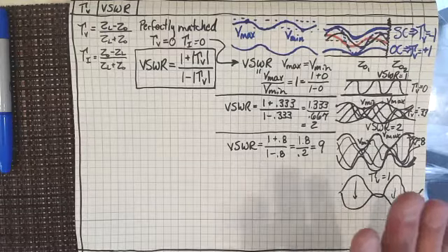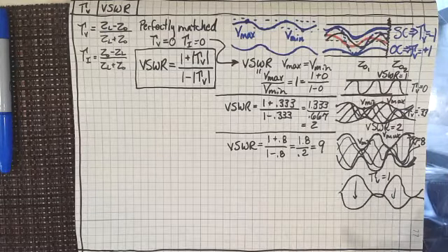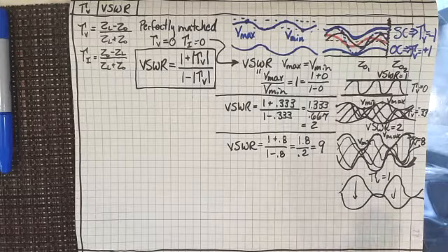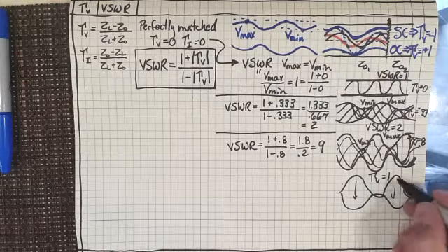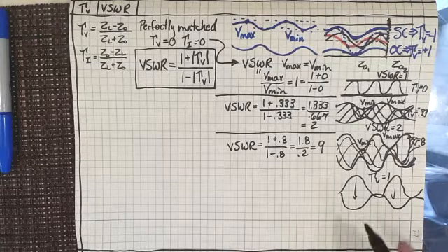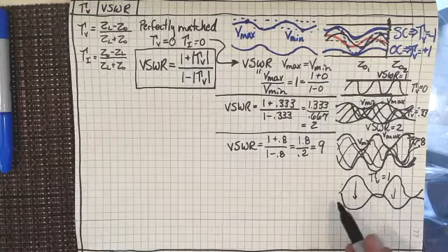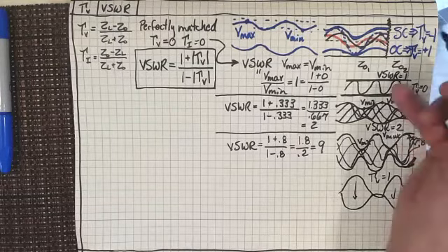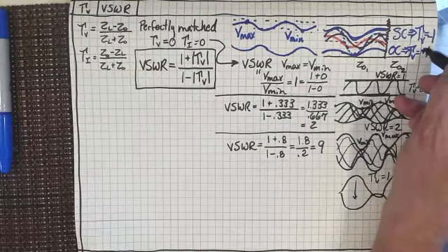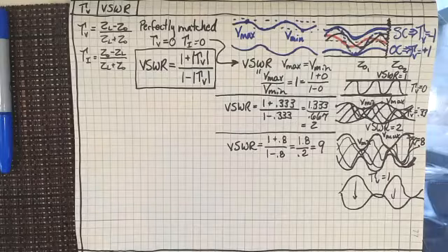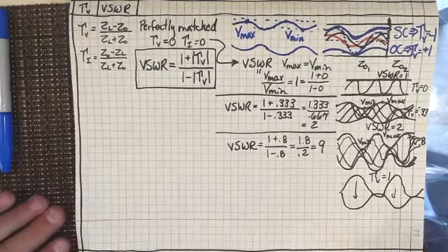And I would recommend looking at the Wikipedia page. Actually, they've got some good things on there too to look at that can show you moving things. Reflection coefficient of 1, and of course this would just be a standing wave, and that would be when everything is reflected back by an open circuit, right? Because an open circuit is going to reflect everything in phase, and a short circuit is going to reflect everything out of phase. All right.